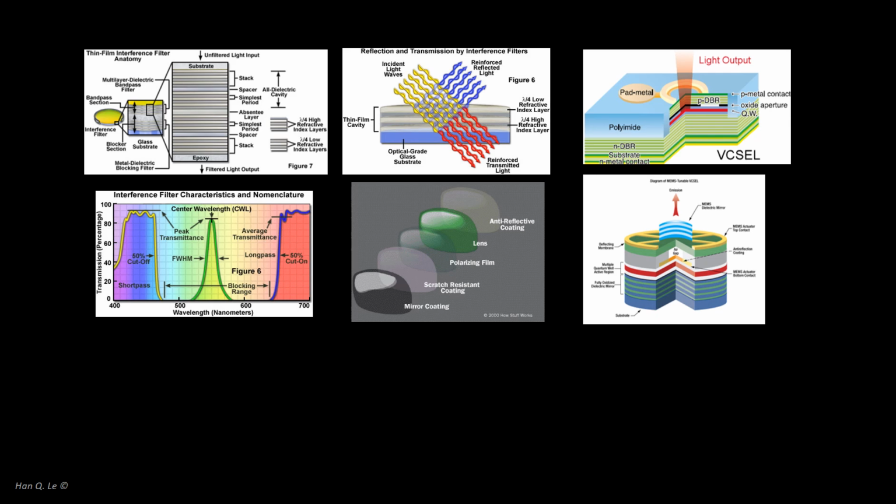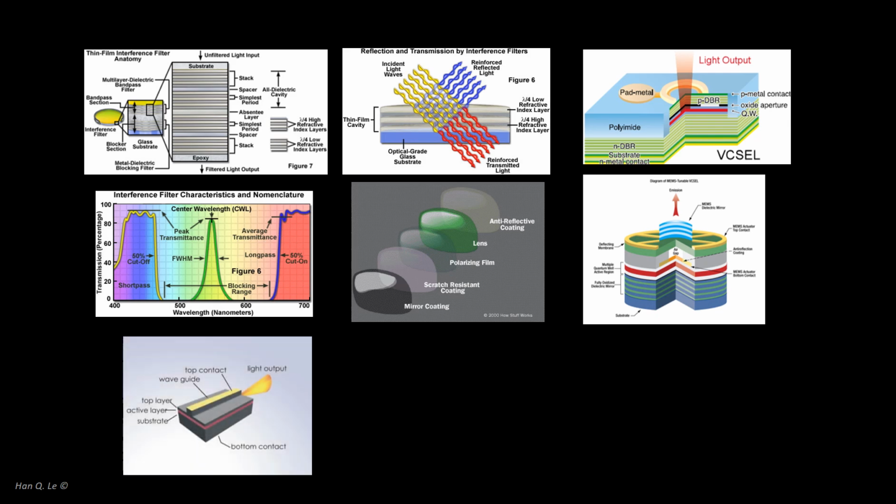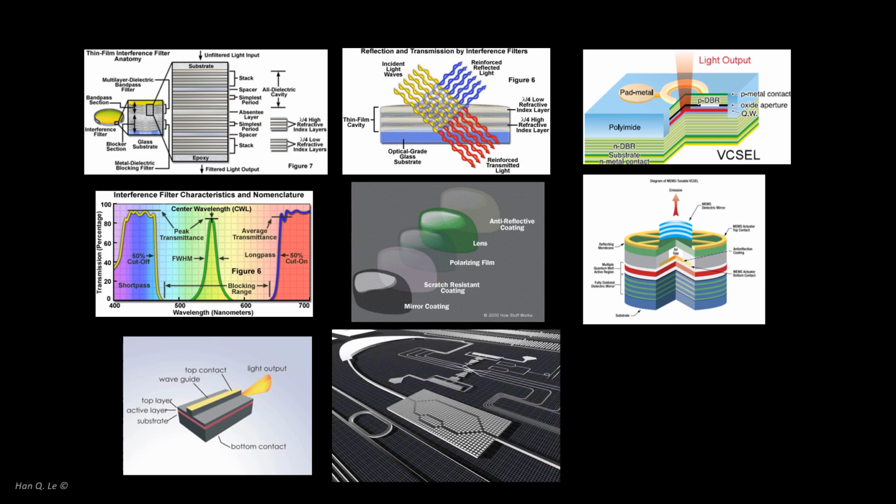The other configuration is for light to propagate parallelly in the planes of the layers, known as planar waveguides. All edge-emitting diode lasers are applications of this configuration. It is not enough to confine light in just one dimension, which is the direction normal to the layer planes, and which is the x dimension in this example. It is necessary to confine light also in the y dimension, and to allow light propagating only along the z dimension as a light wire to conduct photons in a photonic circuit. This configuration is considered as two-dimensional planar, and the mathematics can still be applied as a reasonable approximation.